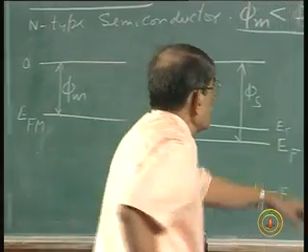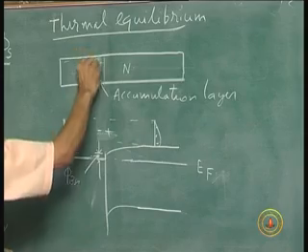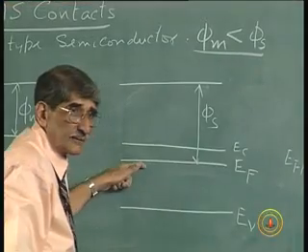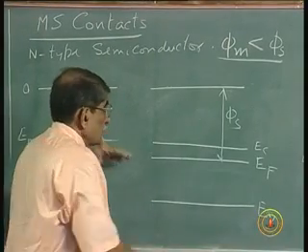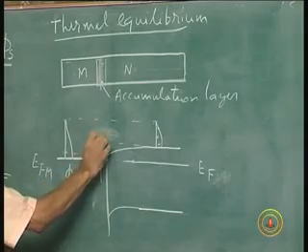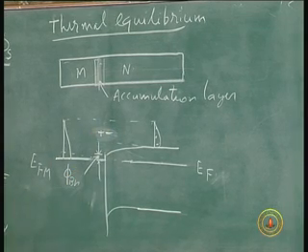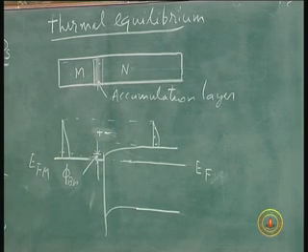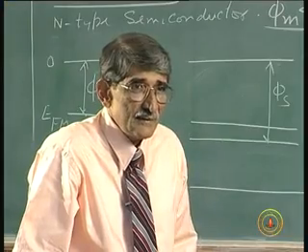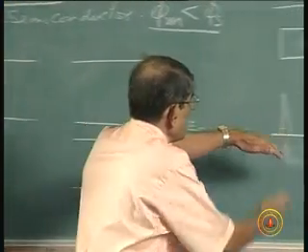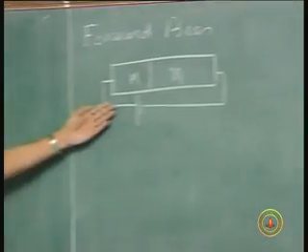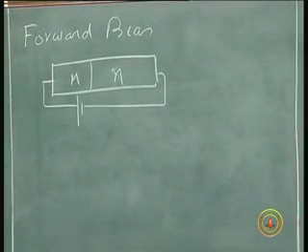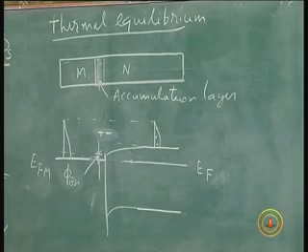In fact, what happens is now the electrons have moved from here to here, charging it negatively. If I make that plus on that side, so now this barrier is like this, I am sorry, polarity is like that, because electrons have gone from metal to the semiconductor. Because of that polarity, I have got this barrier like this. If I make a voltage like this, forward bias, what will happen to this? We are increasing that, it will go up.